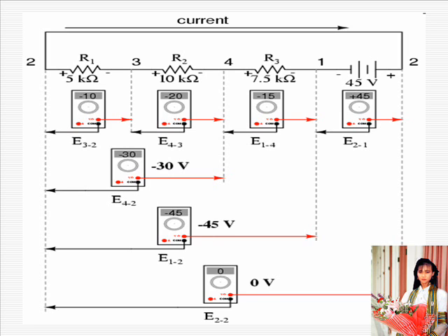We see how the voltages measure successively larger, albeit negative magnitudes, because the polarities of the individual voltage drops are in the same orientation. Positive left, negative right.